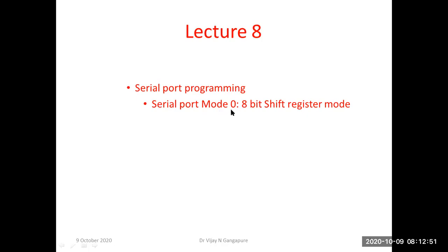So it is simply a shift register mode, or we can call this mode 0 shift register synchronous mode, because 8051's serial pin will get synchronized with external device while shifting data out and shifting data in on 8051 serial port. How that works we are going to study.